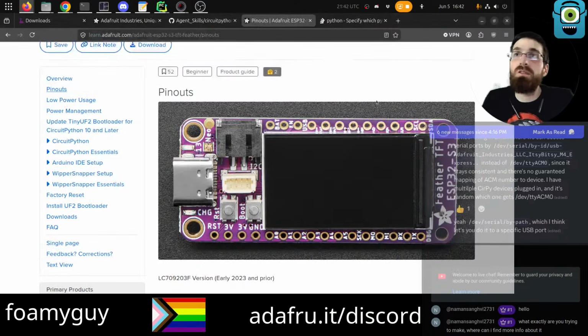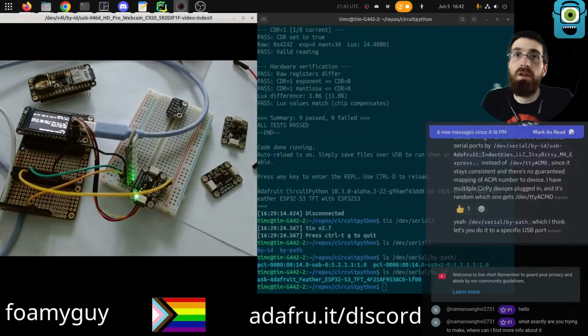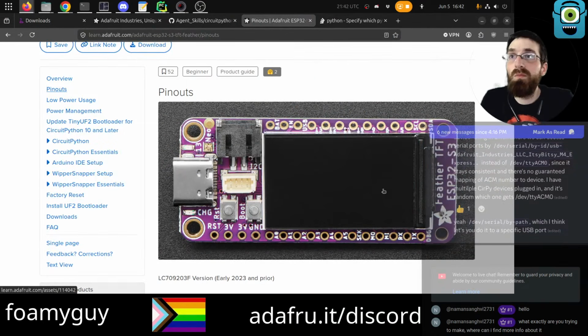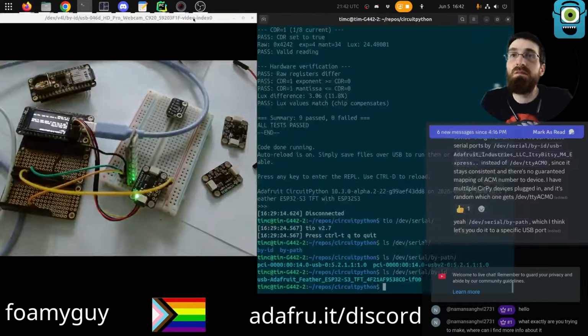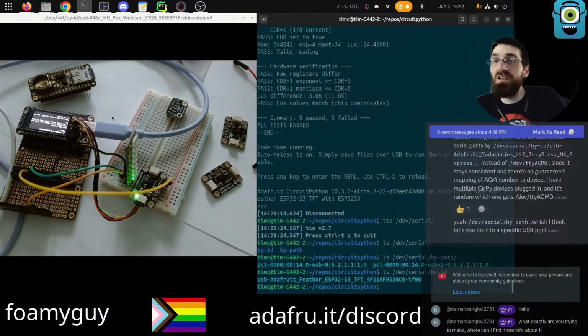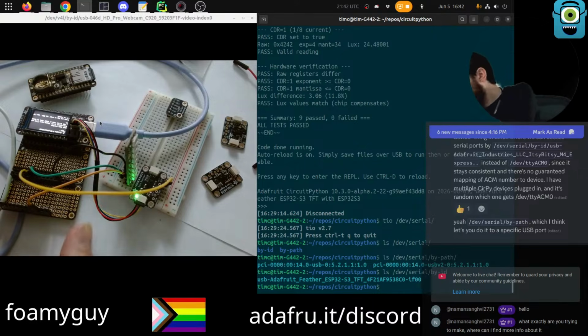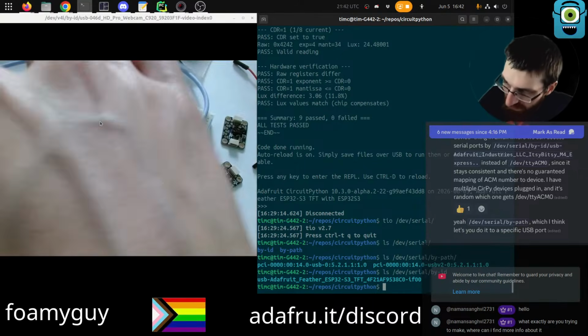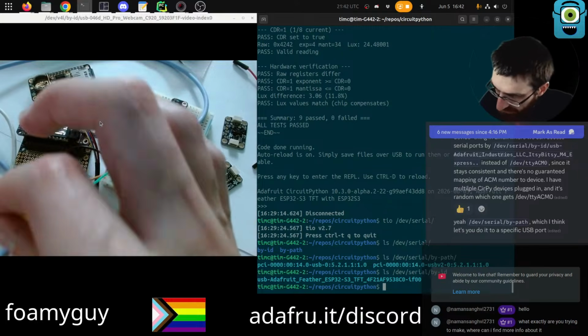They're supposed to be on the short side because they're supposed to be connected to 10 and 11, which are on the short side of the feather, not the long side. So they're actually connected to SCK, MOSI, somewhere in there, which is why it was blinking, because it was using the SPI bus? I don't know actually why it was blinking. Probably just because it's undefined what those pins do and they probably floated or whatever.